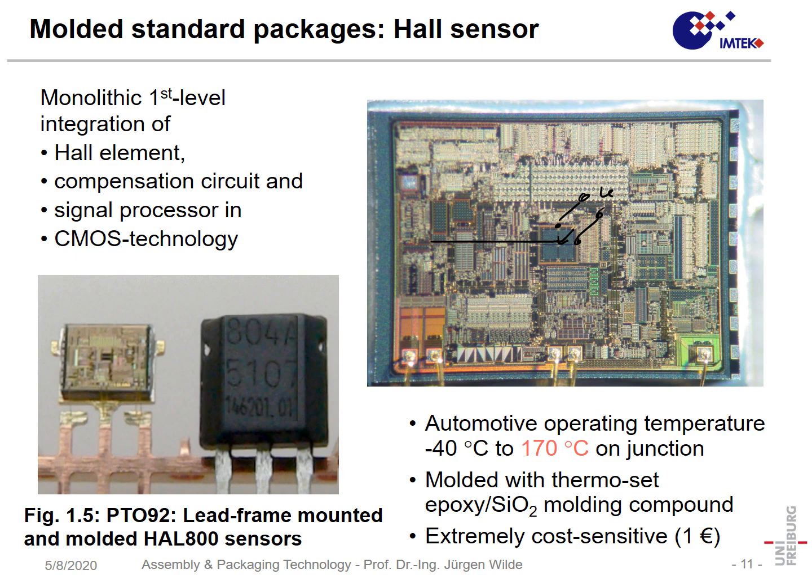But Hall sensors, they worked, but they had many disadvantages. For instance, Hall sensors are very sensitive to temperature, because the mobility of carriers in silicon depends very much on the temperature.